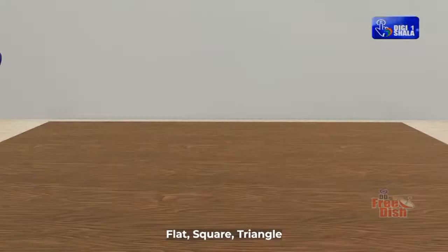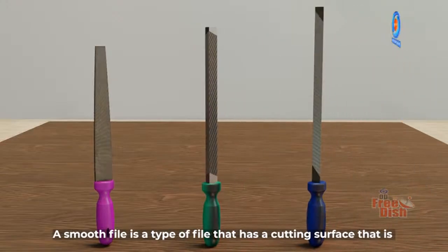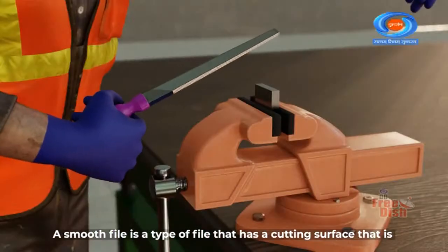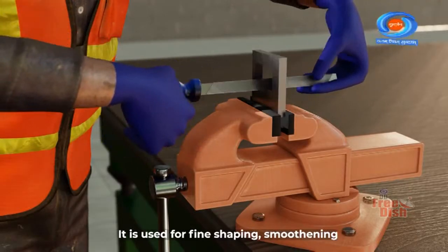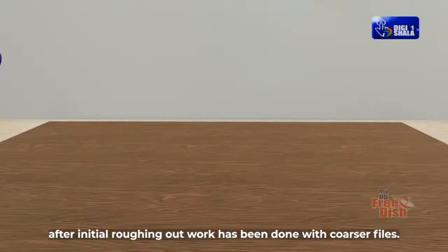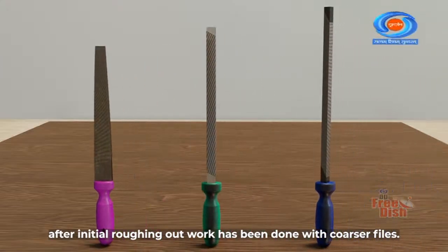Smooth file, flat, square, triangle. A smooth file is a type of file that has a cutting surface that is much finer than rough or bastard files. It is used for fine shaping, smoothing, and finishing work on metal components after initial roughing out work has been done with coarser files.